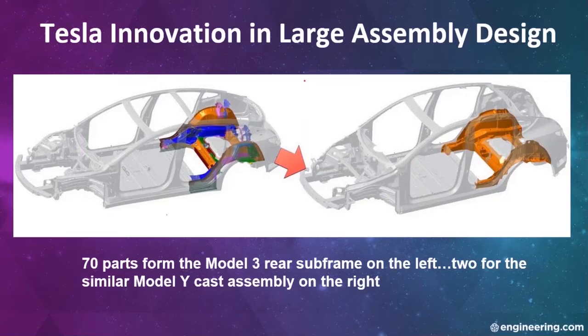At this time, Tesla has released very little specific detail about the system, and much of the photography you're seeing here is based on drone flights and nondescript press materials, but here's what we know right now. Tesla intends to produce vehicles for the European market using a radically different structure than current production. Their new chassis will consist of a floor-mounted battery pack, which is a stressed structural member of the chassis, connected to aluminum alloy die castings front and rear, with the three large assemblies forming a structural support for the body, suspension, driveline mounting, and of course providing the deformable structures necessary for collision energy attenuation.